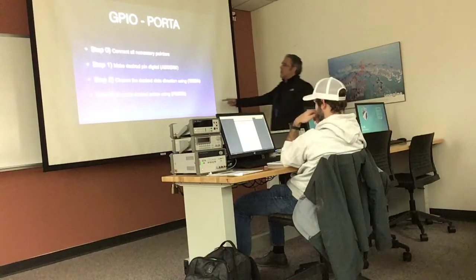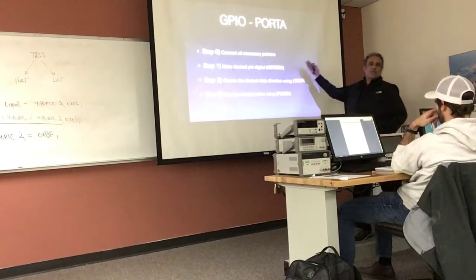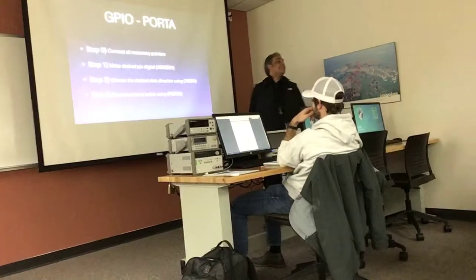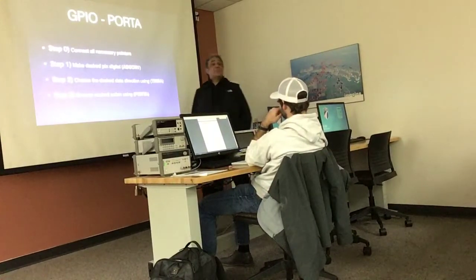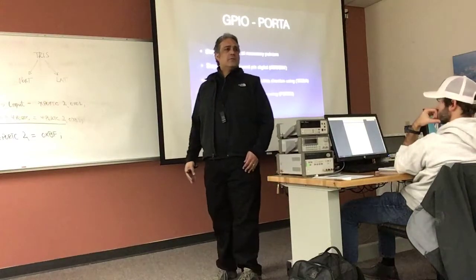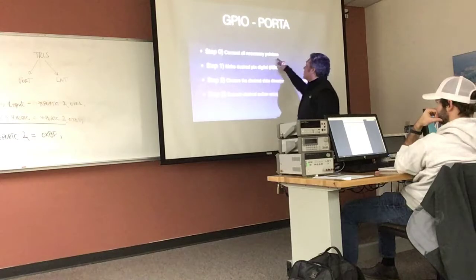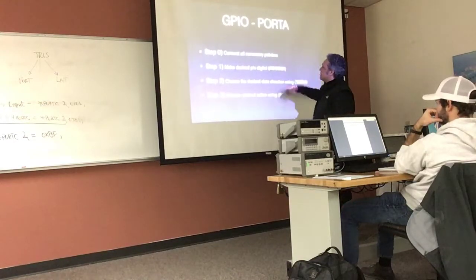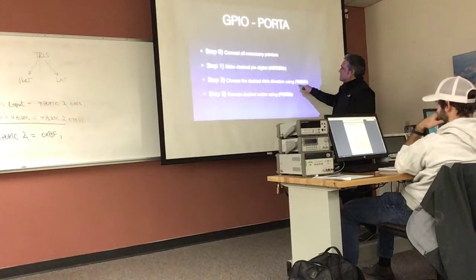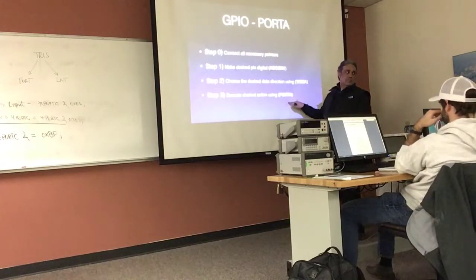So this is nothing more than a reminder. You can actually take something like this and bring it to the test, and use it as your reminder. Somebody says, read an input from port A, or there is a switch connected to port A0. That means there's an input, so I need to connect all the necessary pointers, make the pin a digital pin, set up the tri-state as an input, read. Right? It's kind of like a reminder.